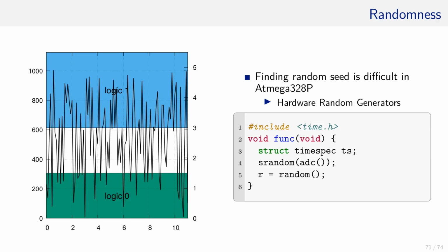The ADC and the noise could be one way to alleviate the problem to some extent. Reading the unconnected and floating pins multiple times, or connecting them to some form of antenna to receive the electromagnetic radiation which is all around us, a random seed could be computed. This seed could show a higher level of randomness than many other options. It might not be secure cryptographically, but probably serves its purpose in many projects.